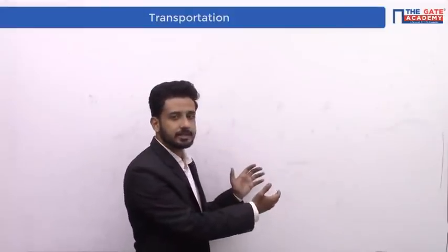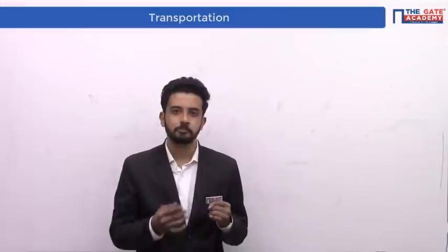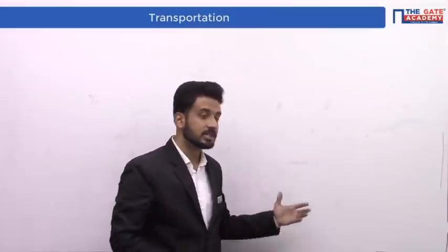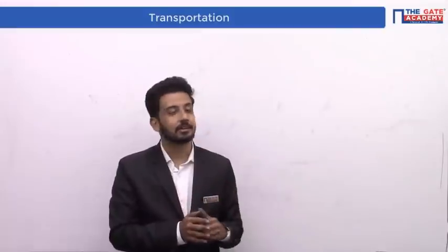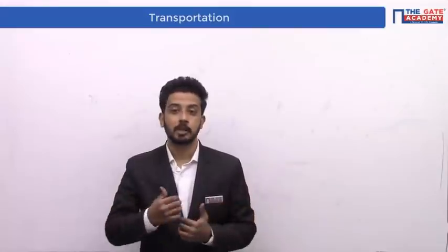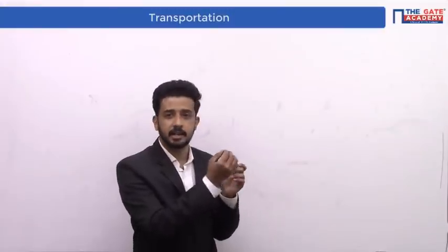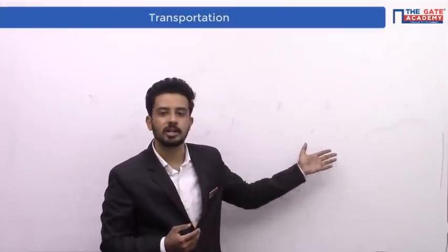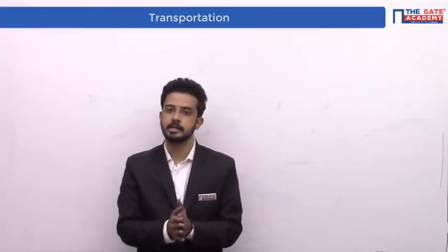Take the example of this last question. If you solve this question, you get a lot of concepts: what is theoretical superelevation, what is actual superelevation, what is cant efficiency, what is its maximum value, how to relate that, and what is the degree of the curve. Maybe in the examination they may ask a part of this question directly, theoretically, for 1 mark, like what is cant efficiency. So a part of this question can be asked in the GATE exam. Like that we have solved a lot of questions.